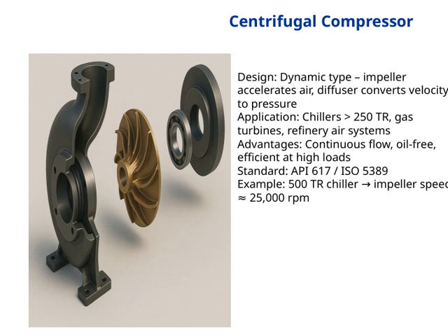One of the biggest advantages of centrifugal compressors is their ability to deliver a continuous flow of compressed air without interruption. Plus, they are oil-free, which is essential in many industries to prevent contamination. They also tend to be very efficient, especially at high loads, making them a reliable choice for demanding applications. Regarding standards, these compressors usually conform to recognized specifications like API 617 and ISO 5389, ensuring quality and consistency across different designs and manufacturers.